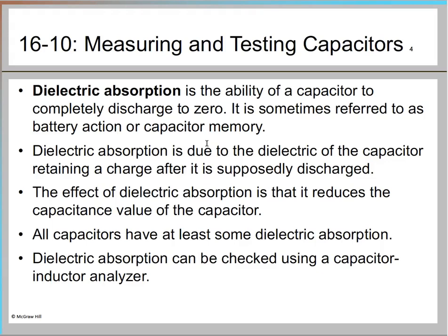So what happens upon discharge? Most capacitors are reluctant to give up all of their charge. Due to this memory, what happens if a capacitor is discharged, let's say by shorting, and then open circuited again? Imagine you have a capacitor and you connect a short circuit, and all the charges will be discharged through that, and then the short path is opened again.